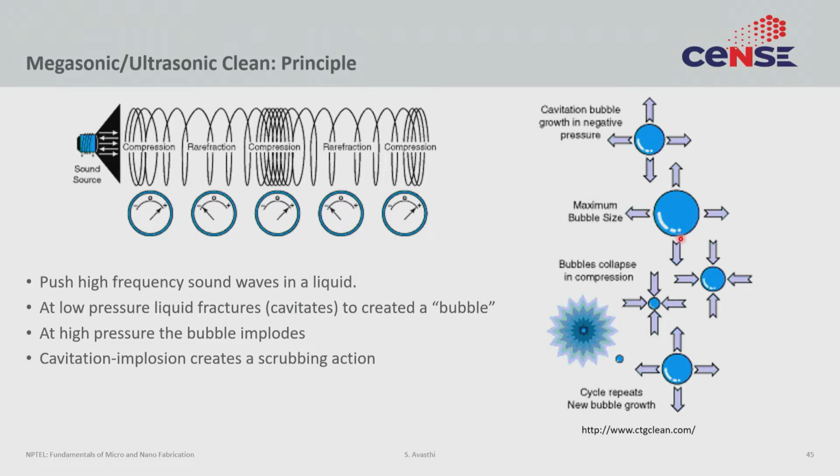If done with high enough intensity, however, this can actually cause cavitation, which, without going into detail, means that the bubble will collapse, and that collapse comes with a significant amount of energy. Think of it as a mini explosion inside the liquid, but it is happening everywhere, and that mechanical energy is what we are going to use to clean the surface.